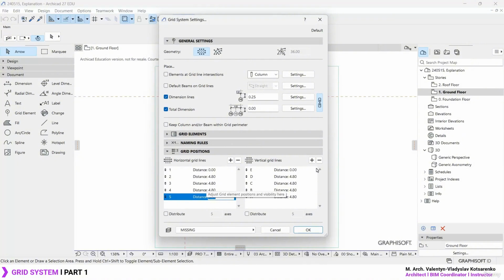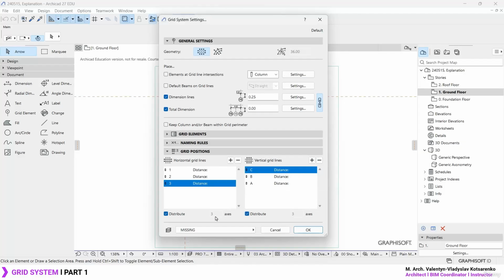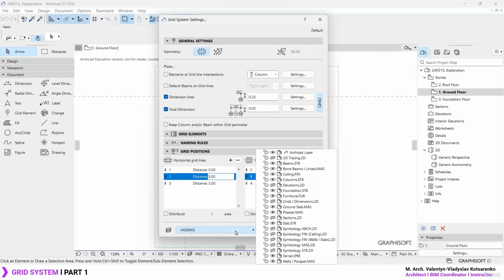Let's simply delete leftover grids we actually don't require. We simply require ABC. And let's simply distribute everything equidistantly. I believe it's going to be much easier. Or simply set the value 3 meters, and pretty much that's it. So let's cross the fingers. Let's see how it behaves.